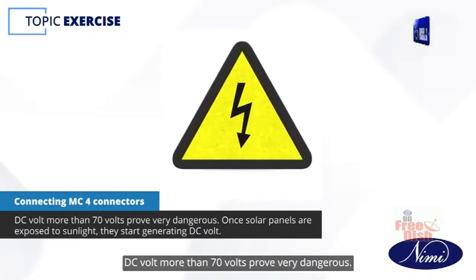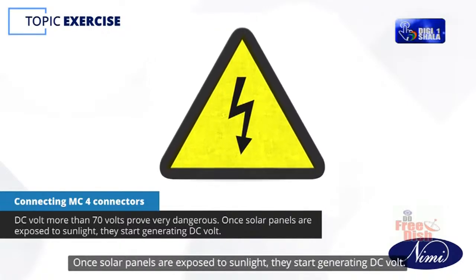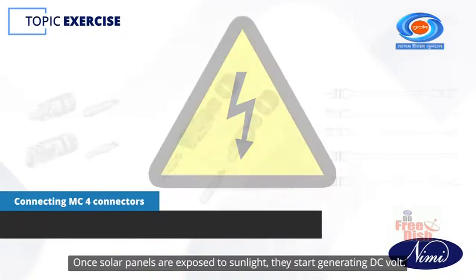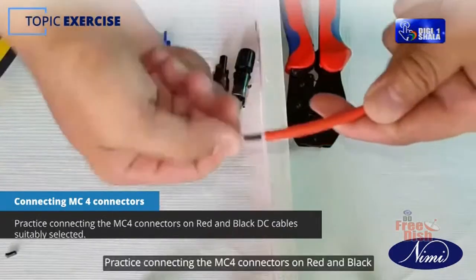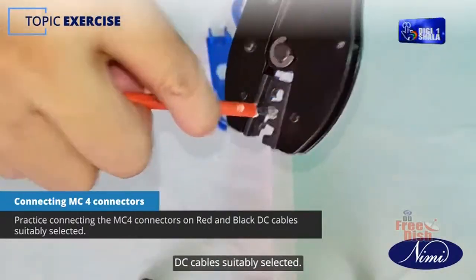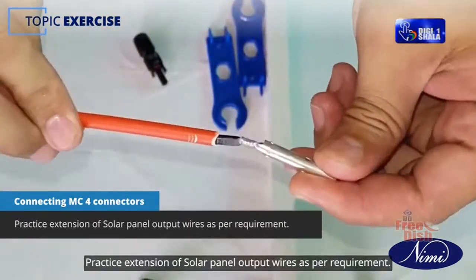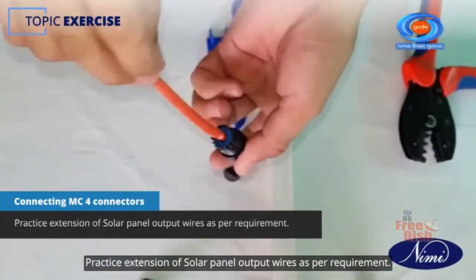DC volt more than 70 volts prove very dangerous. Once solar panels are exposed to sunlight, they start generating DC volt. Study the pictures to familiarize with assembly parts of MC4 connectors. Practice connecting the MC4 connectors on red and black DC cables suitably selected. Practice extension of solar panel output wires as per requirement.